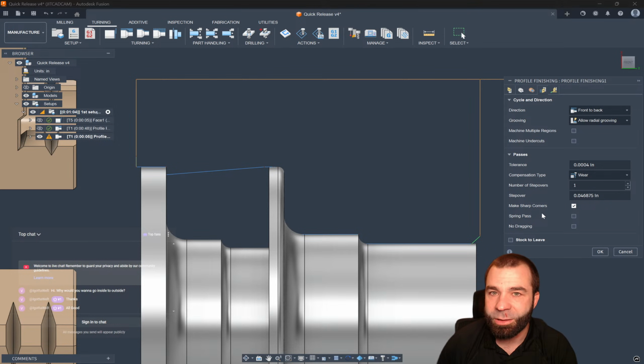Now I'm going to pause here because I always get these questions. Usually on a lathe tool, for most of you, you do not need to adjust cutter comp. You're just going to leave this as in computer, because when you touched off your tool in X and Z, you're possibly going to compensate it there mildly. Now, I say that as a small rule of thumb. If you're running heavy production, you may want to do something like utilizing wear, which would allow you to compensate the wear out of a tool over its lifetime.